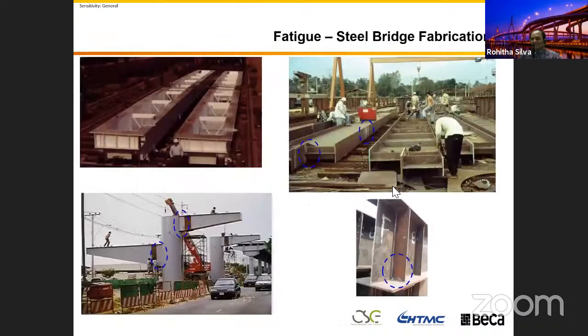This is exactly what I built when I was in Bangkok. This is the real steel construction. And this is the steel fabrication yard. You can see one girder on the top. This girder is 50 meters in length. You can't bring the plate in a 50-meter length. They are 6 meters in length. We just assemble them together, weld them together.